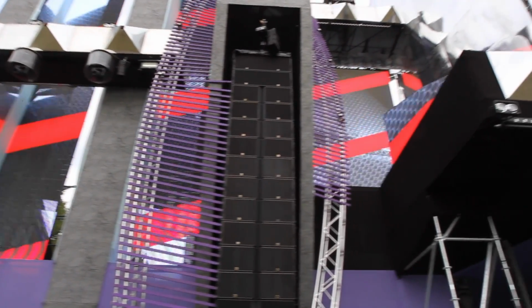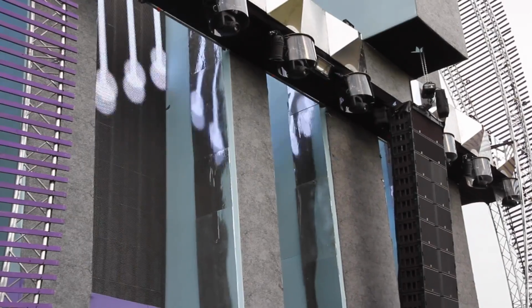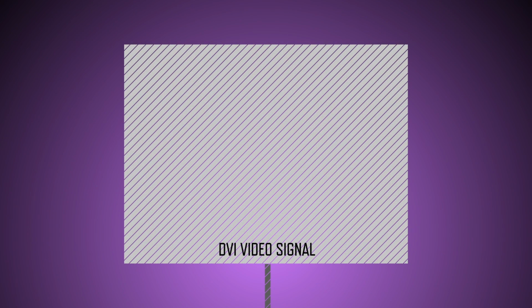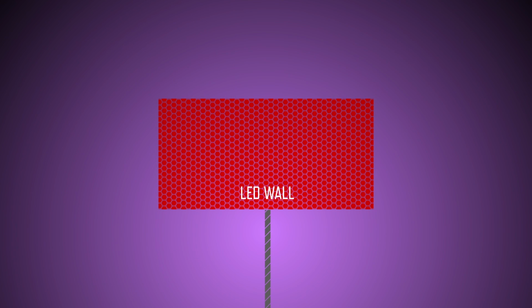When it comes to LED stage mapping, an LED processor usually takes a single video input and divides this signal over the connected LED walls. For example, to set up a single LED screen is pretty simple. The processor takes the top left part of the video signal and displays it on the LED wall or panel.